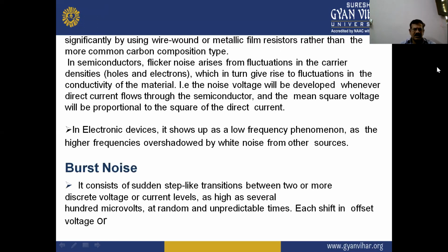And next, popcorn noise. It consists of sudden step-like transitions between two or more discrete voltage or current levels, as high as several hundred microvolts, at random and unpredictable times.